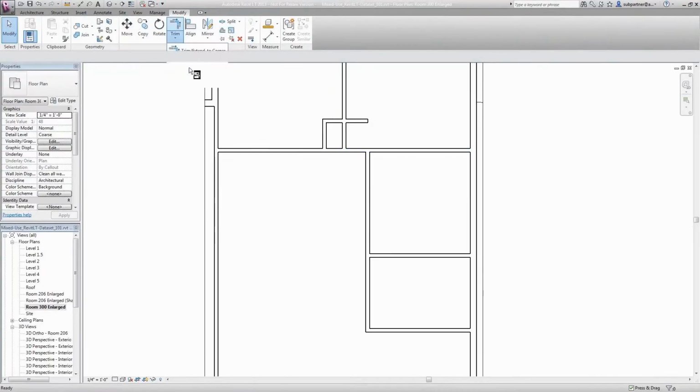So familiar tools like trim, extend functionality. So I can say, okay, I want to trim this wall, similar like if you are trimming AutoCAD lines, but here you are not trimming lines but, sorry, Revit objects, and everything is clear. You can extend again very easily. I want to extend this wall to this wall. Two clicks, done. Everything is very simple, very easy.